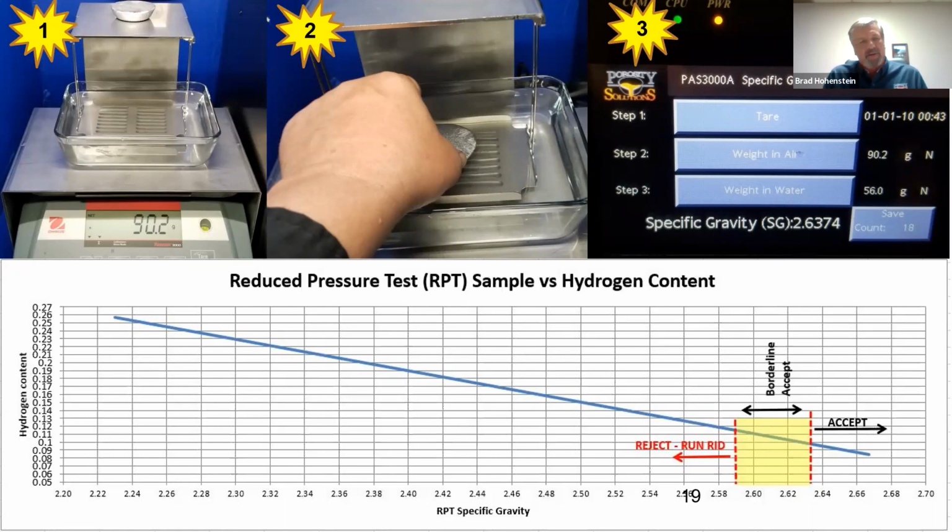If you're thinking, okay, the spec on my 356 is this for magnesium and so on, and you're at the lower end of the range or the upper end of the range in those specs, it won't make a difference. It has very little effect on the, I agree with Brad on the hydrogen porosity. Pushing your chemistries in some different directions will have an effect on your shrinkage porosity, possibly, especially on your levels of titanium, things like that. But like I say, not so much on hydrogen; on shrinkage porosity, your chemistry levels will have an impact.